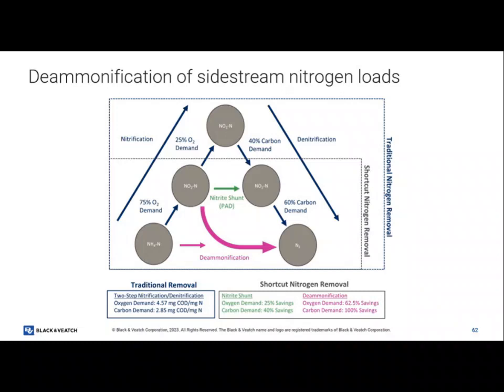Deammonification is the other alternative right now. Deammonification is essentially using Anammox bacteria, and you're taking 50% of it to nitrite. You're not even touching 50% of the ammonium. And you're taking both these in a mix, and this Anammox bacteria makes nitrogen gas without any carbon. So they have a mechanism that basically makes them a very low energy organism.